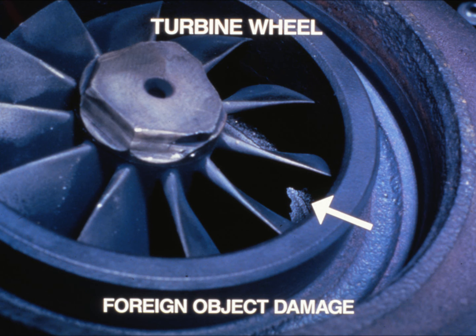The turbine wheel and housing are affected by 4 failure modes. Foreign object damage is one mode. This type of failure occurs if nuts, bolts, or similar debris is left in the exhaust manifold. A foreign object failure can also indicate an engine valve failure or a similar debris-generating internal engine failure.